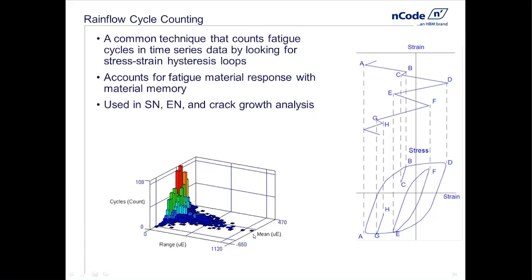Or driving into work, this is expansion joints, left turns and right turns, flying over the railroad tracks, or your teenager driving on Friday night. So with an understanding like this, we have a way now of understanding how many cycles of what size, and that will lead us into what we call Miner's rule for damage accumulation.